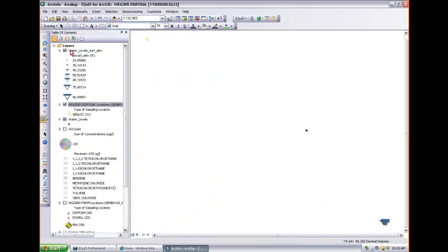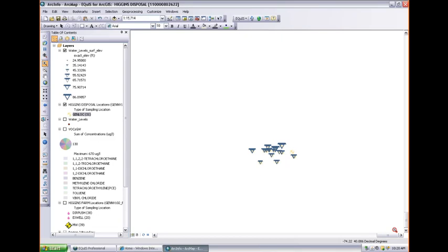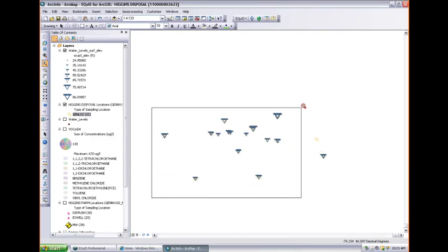There we go. So when you have water levels, we symbolize it with graduated symbols by default, unless they're all null, like the first one. When it's null, I don't know how to symbolize it, so you get black dots. That's why you get black dots. If you query all chemicals and don't cross-tab it, black dots. You can use any of the ArcGIS tools to symbolize it yourself. It's like any other layer.